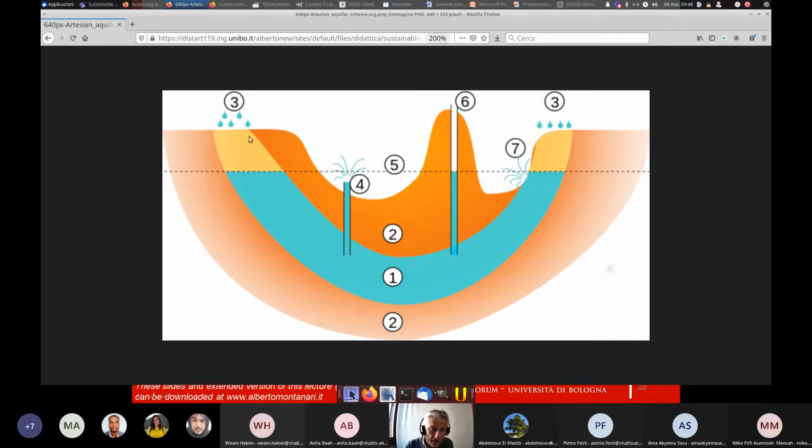The yellow layer is a permeable layer, while the red layers are impervious. So it means that you cannot have infiltration in the impervious layers, but you can have infiltration of water in the pervious layer, in the permeable layer. So you get water flowing into the ground by following my mouse here. And then it gets stored underground, typically between two impervious layers.